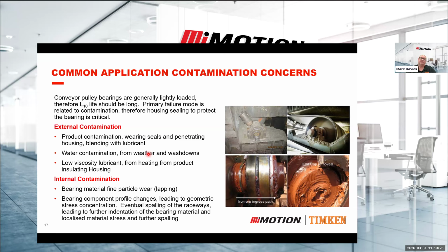It wears the seals out, and then you end up with the lubricant getting contaminated with rock or with water or both, which causes problems with viscosity. Also, if the housekeeping isn't very good, you can get large volumes of dust building up over the housed unit and insulating it as well.